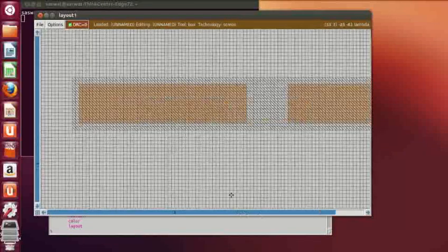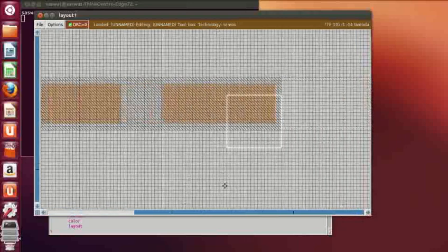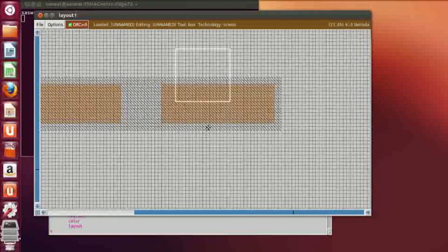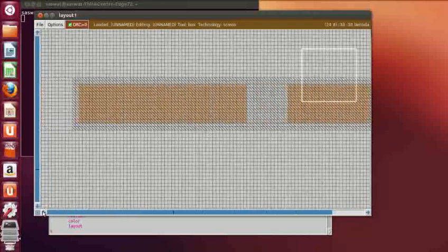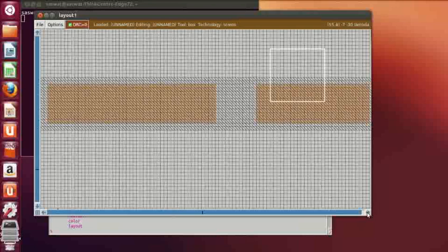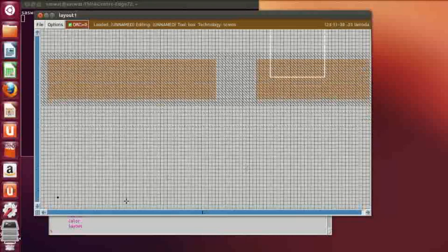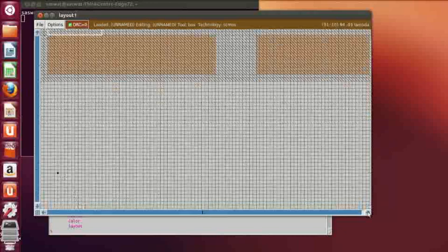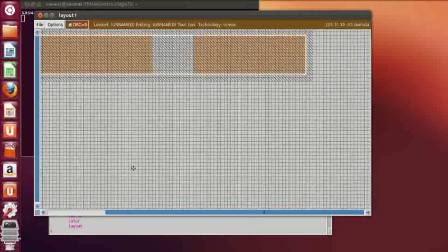Now similarly, we can make a rough idea over here. Here there will be one poly, here there will be the second poly. These two will be the sources. This portion will be the common drain for two PMOS. Here this is one gate, then a source terminal and a drain terminal. But in the case of the NMOS, we have the source and drain. The source and drain are common for the first two NMOS, and the source of the second and third NMOS is in common. So we can directly select from here to here.